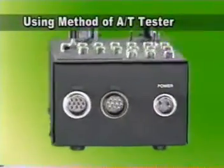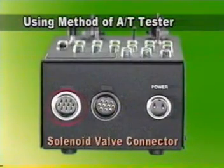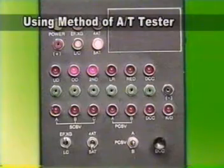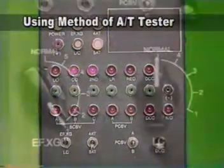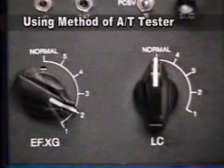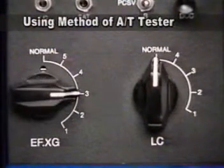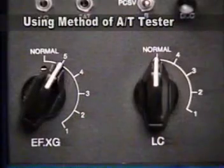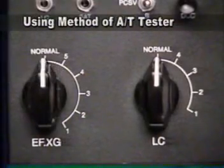Connect the auto tester power to the battery and disconnect the solenoid valve connector. And connect both harnesses together. Then installation is completed. Select the vehicle model and 4 automatic transaxle or 5 automatic transaxle and select the appropriate gear ratio. Then any speed is feasible ranging from 1st to 4th or 5th speed.